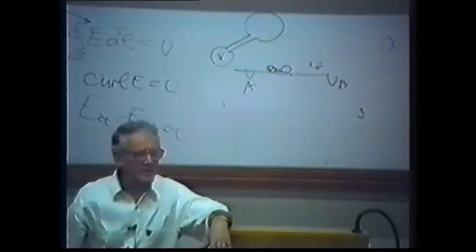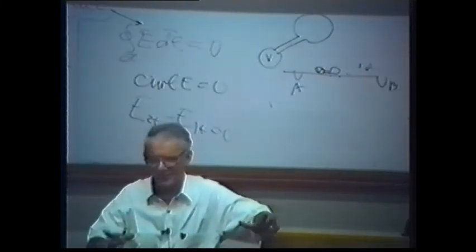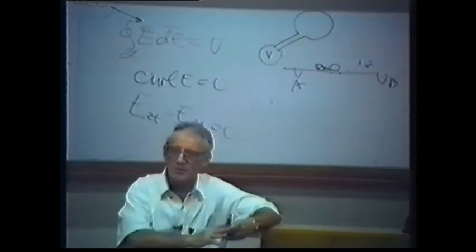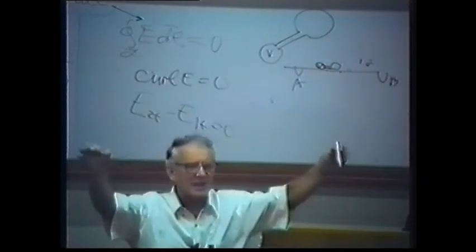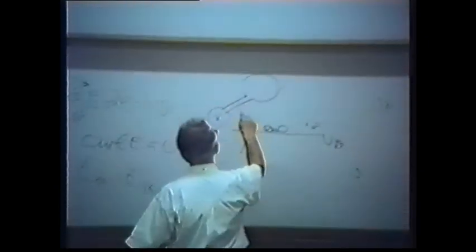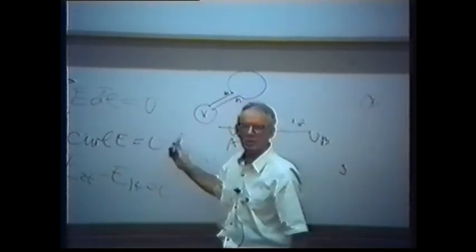Everybody saw a four electrode array in electrical methods. I mean mainly for students. I don't want to offend engineers now. I mean students. So you are in the field. You took current electrodes A and B, created an electrical field. Now, why do we have to use other receiver electrodes MN? Let us take a loop, a nice loop, 1000 turns, or 1 turn as you wish, connect it with a voltmeter, and without grounding measure what?